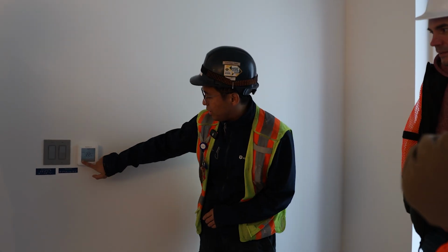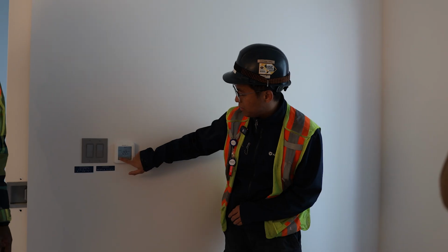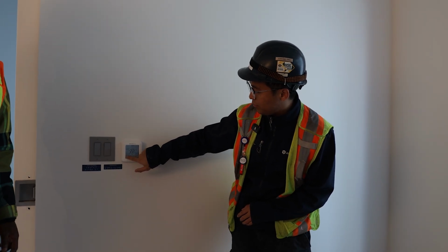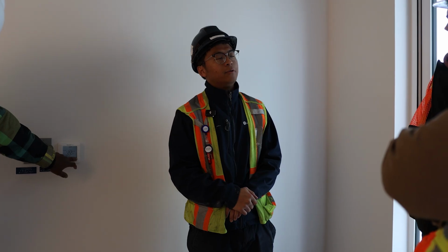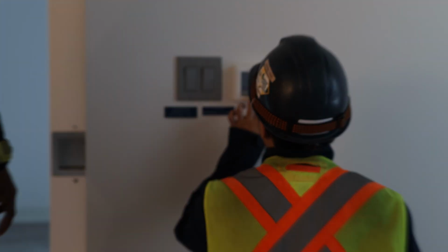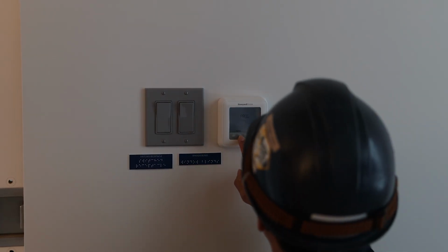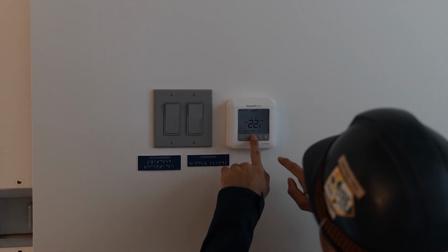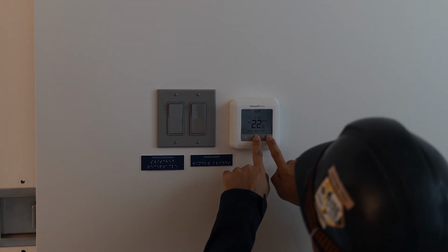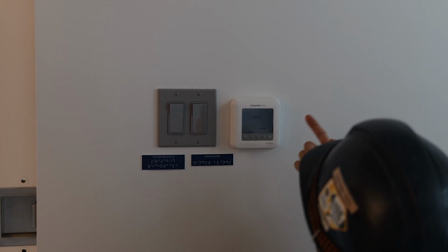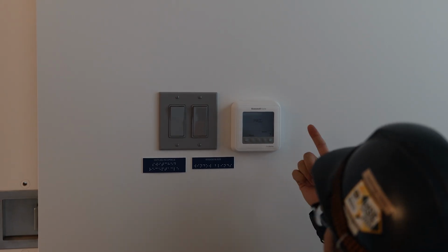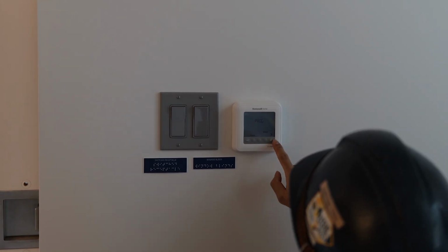You can change the set point on here just by pressing plus or minus if you want to lower the set point. Maximum 25. Yes, you are able to do it. I just need to refresh my mind a little bit. There we go. So I think you need to press the center menu button, and then press plus. Then we are in the program setting.